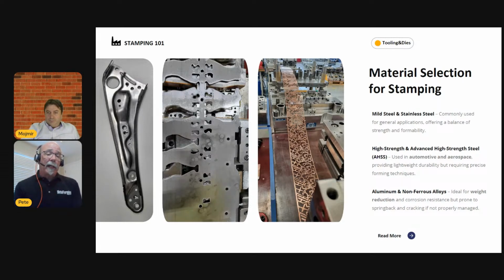Now I'm cutting a high strength steel that has these little particles of martensite in there. What do you think that's going to do for die wear? Yeah, it's very, very abrasive material, very abrasive for cutting, very abrasive for forming. Again, this goes back to understanding behaviors of material and understanding material properties.